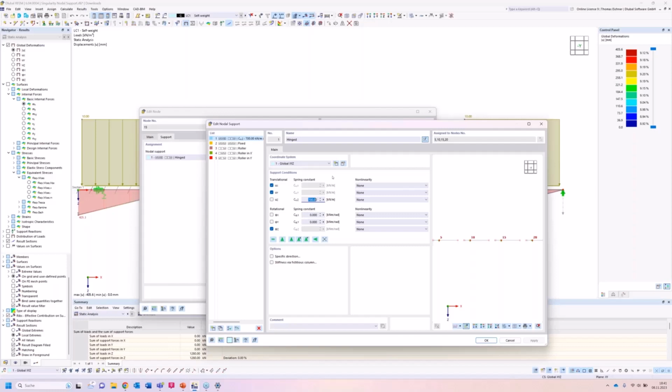You can also just go for the spring constant value, but like I said, there are a lot of insecurities in material, in everything. That's why there's this factor for concrete of 1.5, so a 50% safety factor for the material.